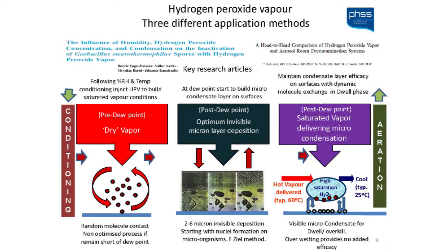And here's the big but, and a lot of people get confused about this: the whole process is not like spraying something on a surface. Like you take a spray and you get a microcondensation or whatever. That isn't the process at all. What you're getting is saturated equilibrium, vapor pressures, and saturated equilibrium. In equilibrium, we'll get as many molecules arriving on the surface as leaving. So there's a dynamic exchange going on all the time. It's a completely dynamic process.